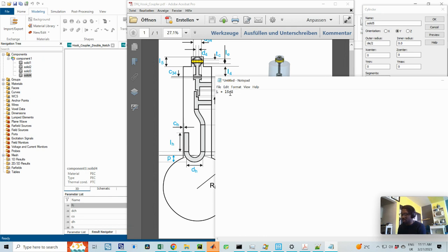So for the top point, that's y max, would be equal to this, then plus, now what's the length of the cylinder itself? It's LE, so plus LE divided by 2, and then just go ahead and copy this, and then y min would be L5 minus LE over 2. So this is how I do my calculation. I'm going to be using this a lot to position the components.